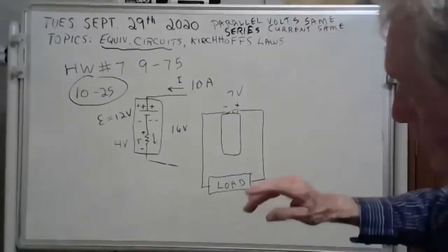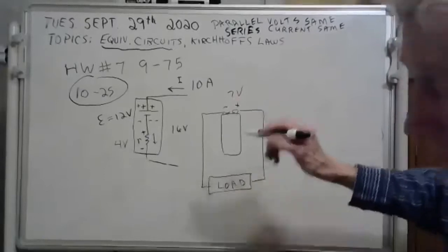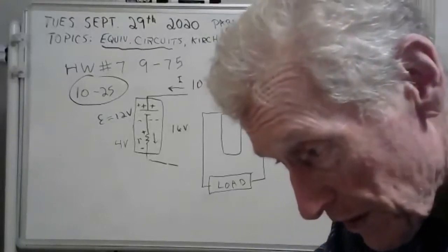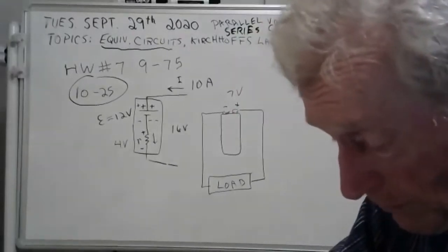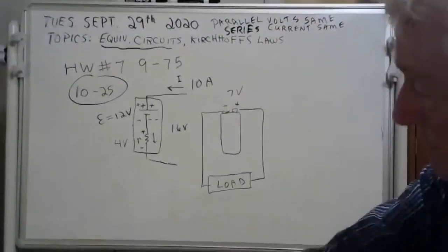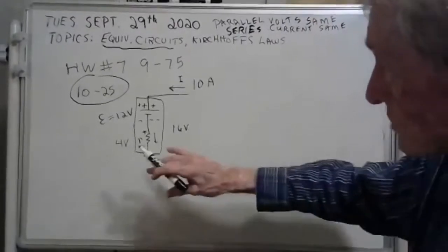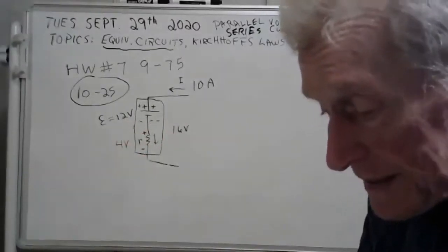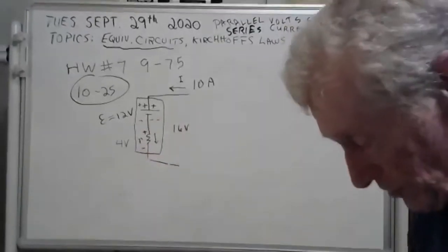Yeah, because what happens is your voltage goes down. It was a 12 volt car battery, but once you started that ignition and you got your starter motor, it uses up some of the power, and you don't have 12 volts anymore. It goes down. But see, we're doing just the opposite here. We're charging this thing. This was a 12 volt battery, but now it measures 16 volts, but we're charging it. And we have 4 volts across the internal resistance.